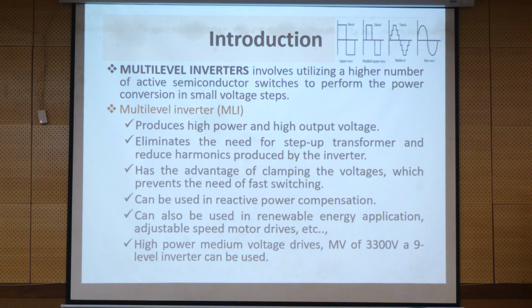This can be the advantage of making use of a multi-level inverter. It produces high power and high output voltage with the same rating of the power semiconductor switches, which can be cascaded, making use of multiple units in series connection.